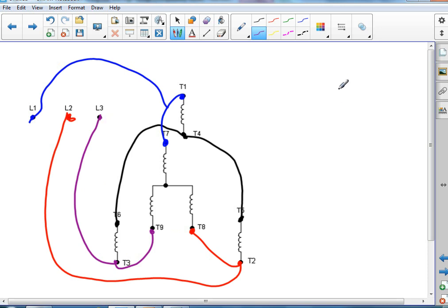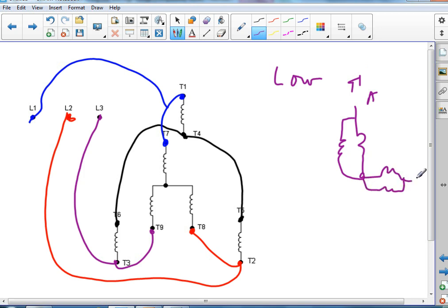So what you end up doing in a low voltage configuration, which is anything less than 480 volts, is you end up having your coils in parallel. So that'd be phase A, T1, and you have coils in parallel, phase B, T2, your coils would be in parallel, phase C, T3. So that's what you've done. You've hooked those together and hooked them up that way.